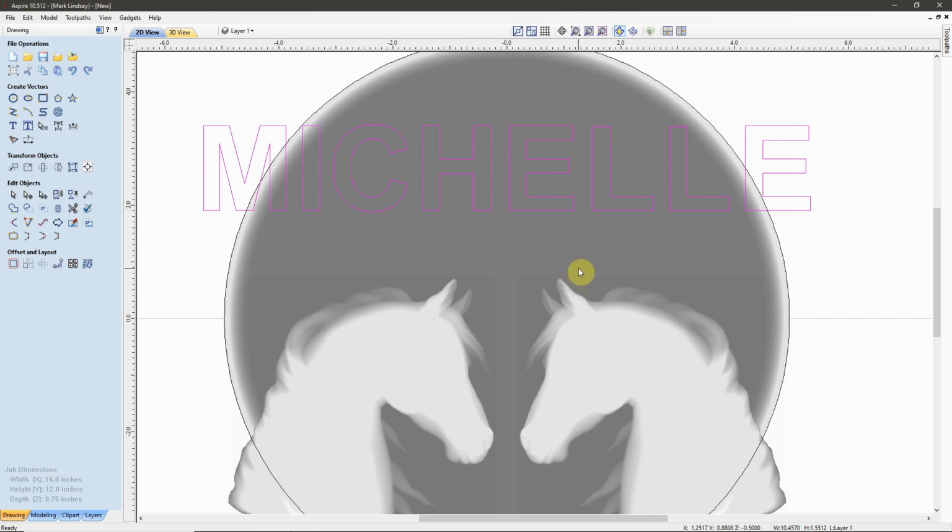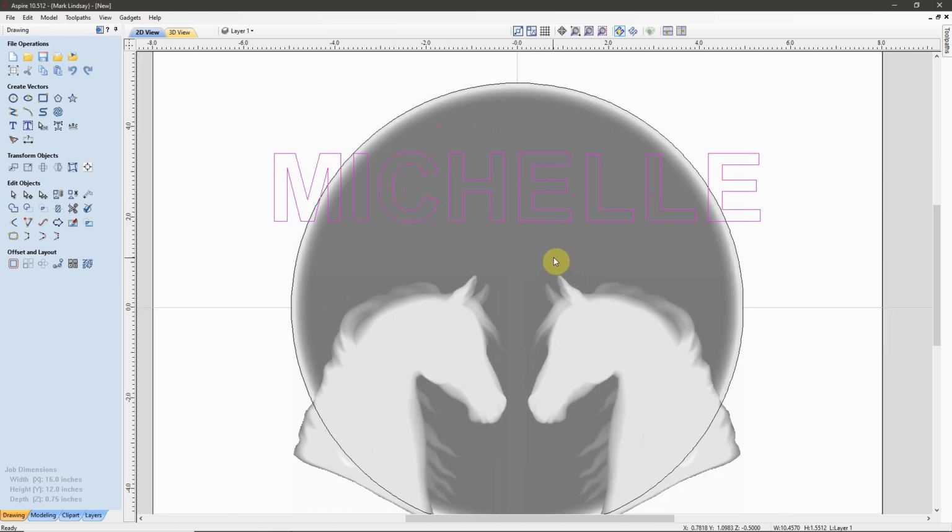And now I want to place my text upwards a little bit, and I want to make sure it's centered within the dish. So I'll go over here, click it again to go into Move and Transform mode, and let's bring this up. Now, as I move this, pay attention to these vectors where they interact with this dish shape.